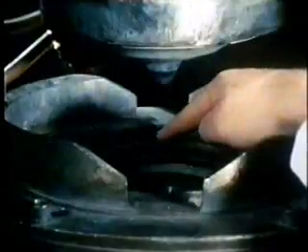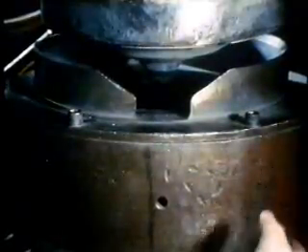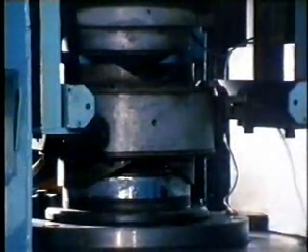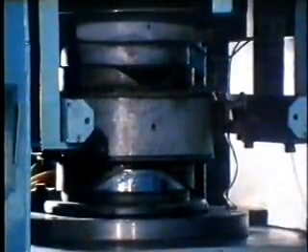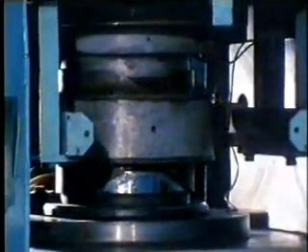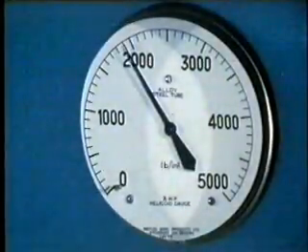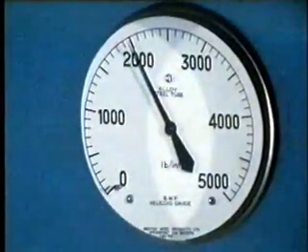The capsule is placed in the center of a high-pressure die in this hydraulic press. At the top and bottom, two horizontally opposed tungsten carbide anvils. At the back of this press, heavy braided copper leads give some idea of the enormous currents which pass through the anvils to generate the necessary temperature. When the right pressure and temperature conditions are reached, the metal melts and acts as a solvent, recrystallized in the form of a diamond.